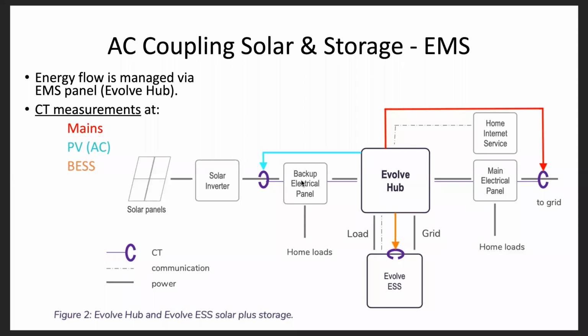And after the standard 5-minute synchronizing timer goes, that solar inverter will then start serving those backup loads in an off-grid mode, and any excess PV generation will go into charging the battery in that microgrid type of setup.